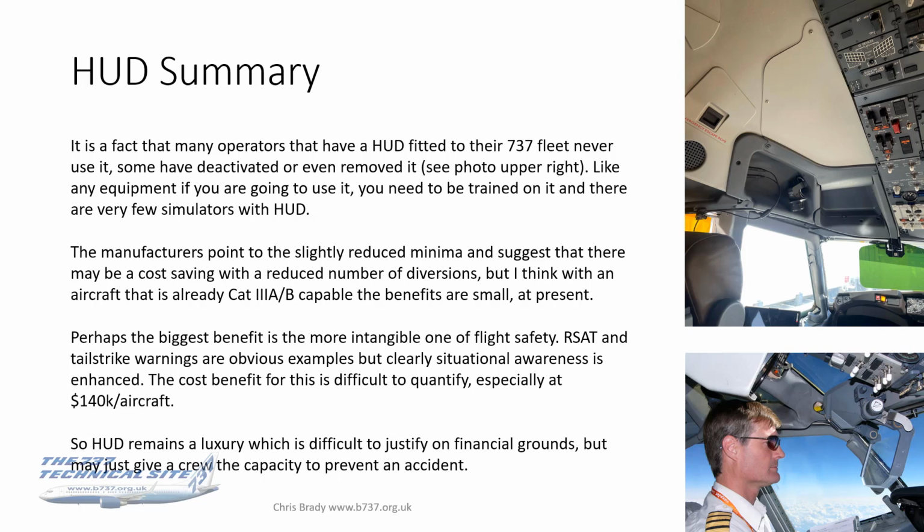So it's actually quite difficult to keep crews current at LVP ops with the HUD. If they're not current, then can you really use the lower minima? Would you want your crew using the lower minima? So really, it's coming down to is it practical? Are the gains really there? Now the manufacturers will point to the slightly reduced minima and suggest that there may be a cost saving associated with the reduced number of diversions because of those reduced minima.